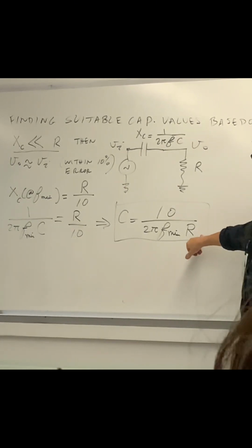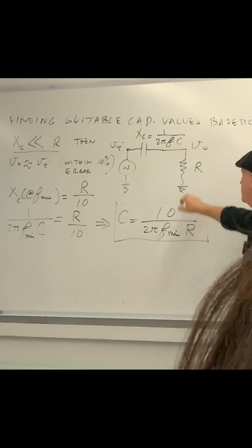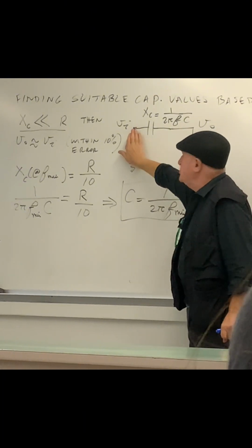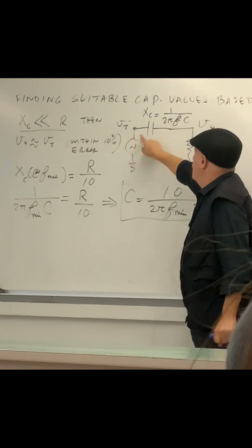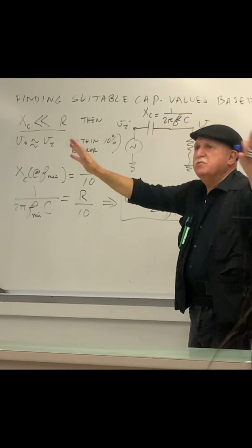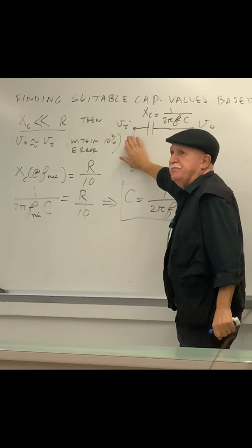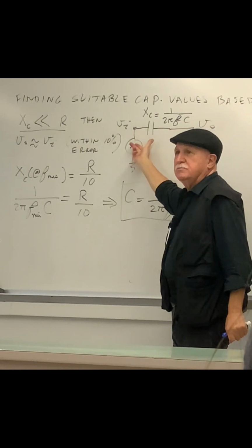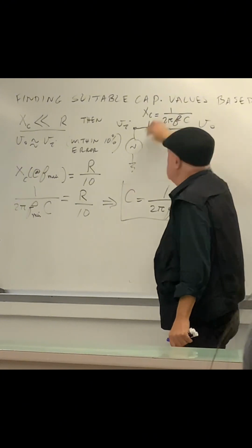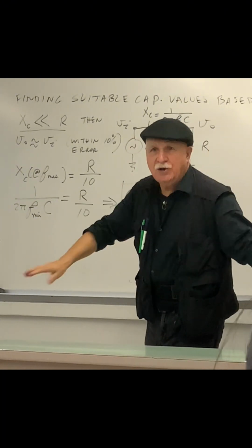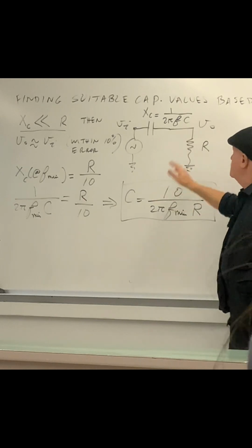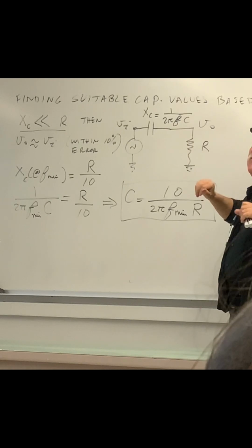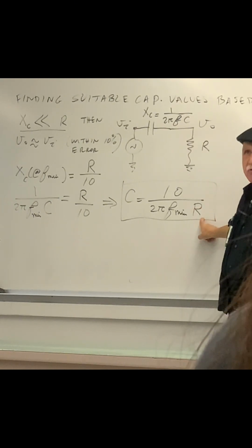You will look at what is the accompanying resistance. And how do you know the accompanying resistance? Short circuit the source. What goes in series or parallel with the capacitor, it doesn't matter. If you short, this end turns to here, R goes parallel. You can also look at it as R in series. Whatever resistance goes parallel or series with the C, that is the resistance under consideration.